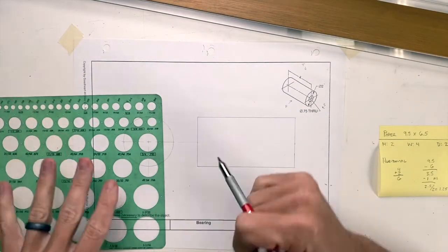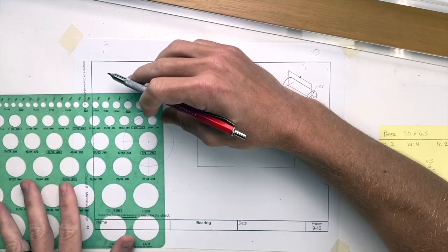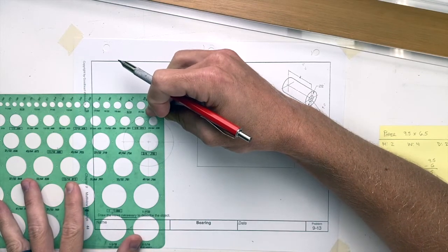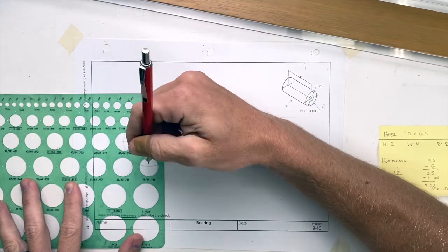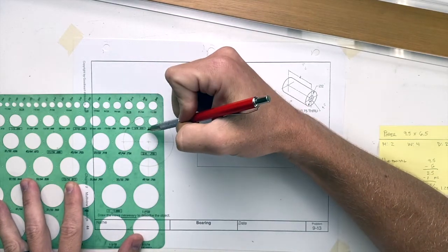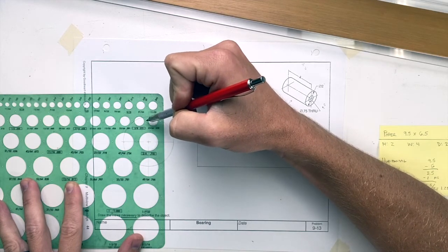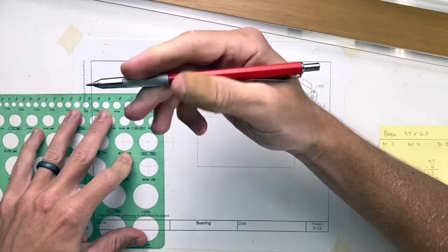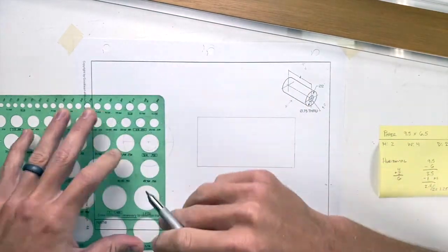I'm going to line up, there are 3 holes on all sides of my circles, so I line up these 3 holes with my center lines. So you look down until you see there's lines in your marks. You might have one that has little tick marks. Some of them even have tick marks on all 4 sides. Just make sure you're not confusing it with the one next to it. So if I'm looking at these, make sure I'm not lining this hole up for this circle. So that looks good. Make sure your graphite holder is nice and sharp. And strike your circle.